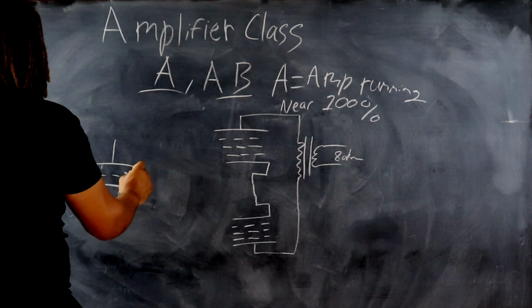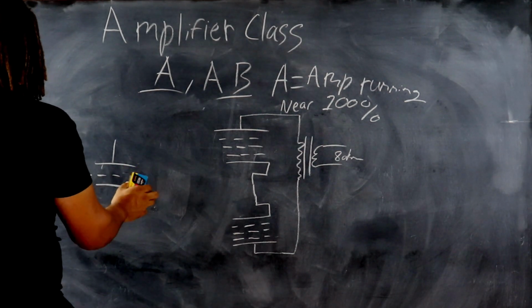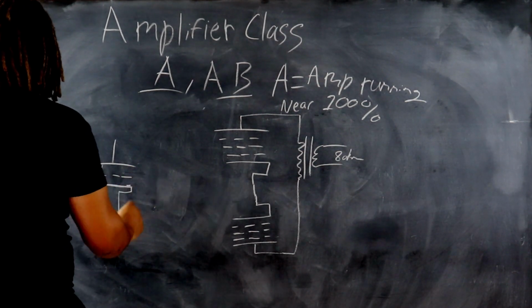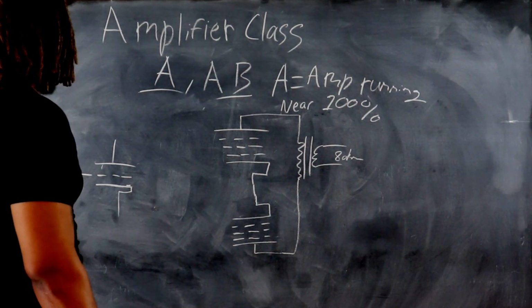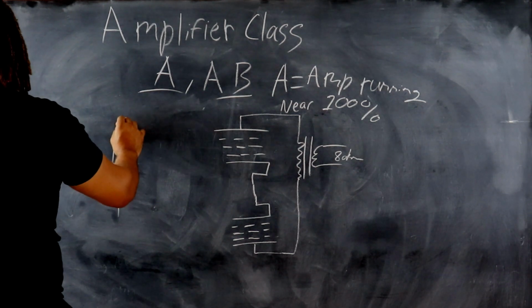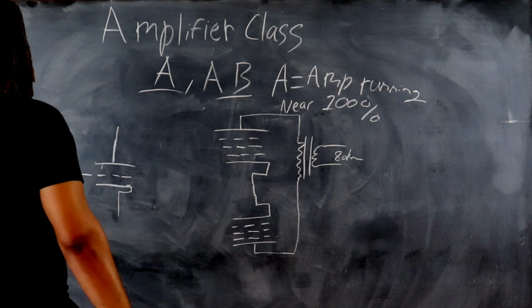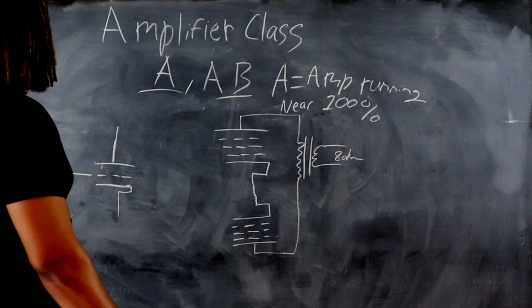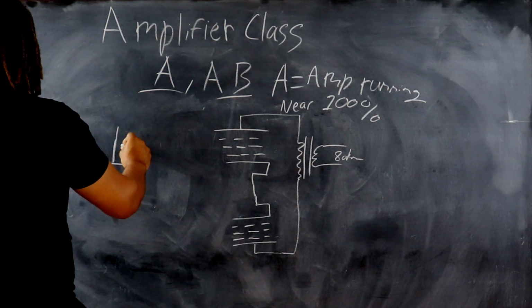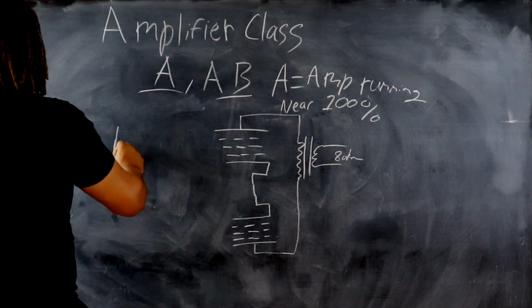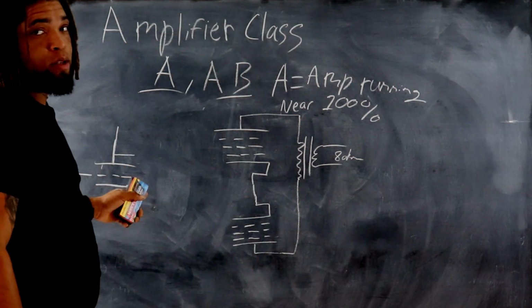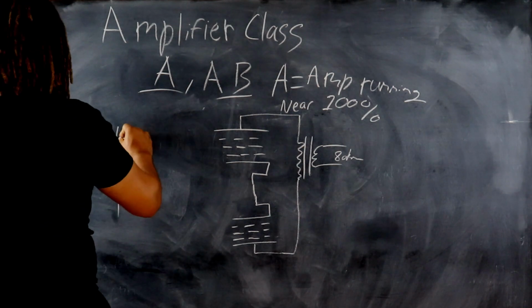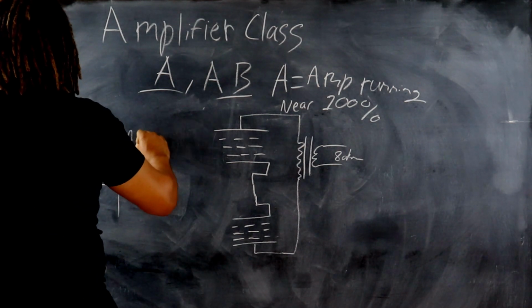and that'll come through the first gain stage. But in this case, it'll be a phase splitter. And all that means is that instead of a typical gain stage where we'd come out of the plate, here we're going to come out of the plate, which of course is going to be inverted. So we're going to have the same signal, but upside down, basically, right?